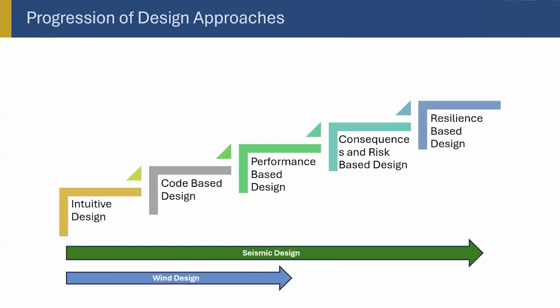For super tall buildings, it's the opposite. Earthquake has much less effect, but wind has all the effect. So at a certain height, below that, earthquake governs. Beyond that, wind governs, and there is an overlap region, depending on the location of the building, where both earthquake and wind will fight. And that is the most difficult region. And the 100 to 150 to 200 meter tall buildings are in that region, where earthquake and wind both are critical, and they're fighting. When you cross 300, wind will take over.